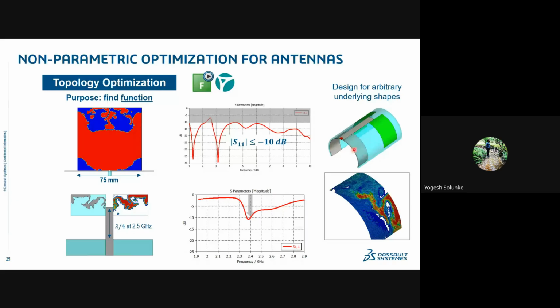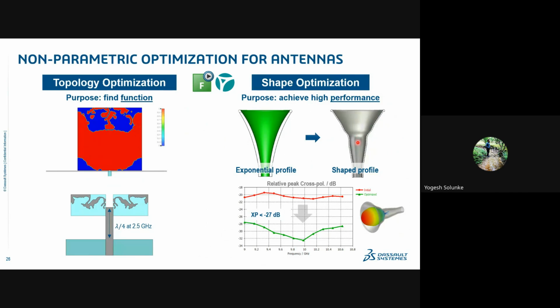Going further, if you want to do any bending analysis of your component, that is also possible, and you can do it here in CST. Shape optimization you can also do. This talks about a horn antenna again. If you have designed a horn antenna and you want to bring some novelty into it, with the help of this shape optimizer, which is available with CST, you can modify its shape in such a way that you will have a similar result. So this you can also do here.